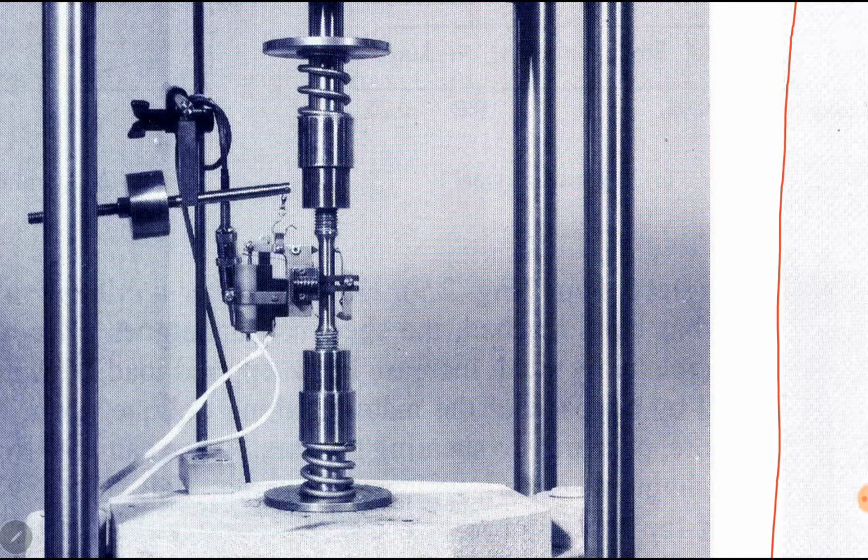Fatigue means failure of material under repeated loads, under alternating loads below the yield strength of the material. So for that we draw SN diagrams. S stands for stress and N stands for number of cycles of load. The horizontal axis of this diagram shows number of cycles of the load. They are mostly in thousands or millions or billions. In 10 power, it is logarithmic scale. 10 power 3, 10 power 4, 10 power 5, up to 10 power 9 or more. This is N, number of cycles of load.